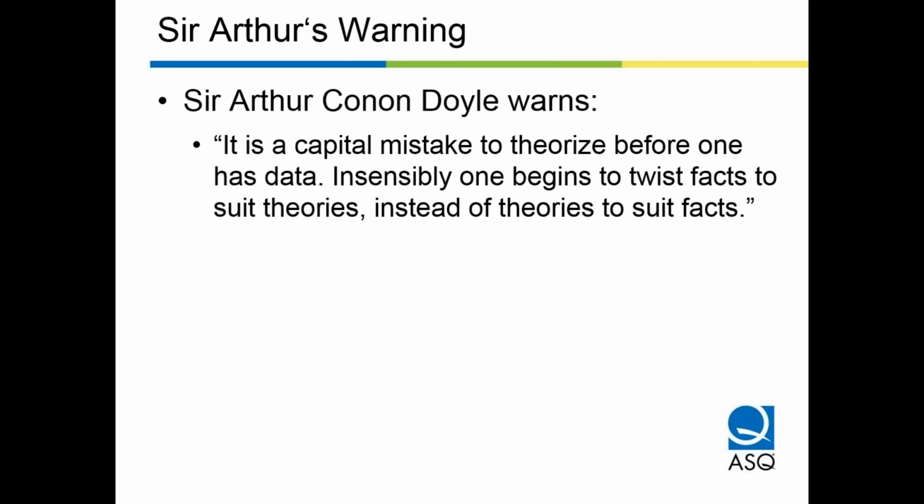Look at it, interpret that graph, form a hypothesis, by the way, using induction. Then evaluate it empirically. If the root cause is not identified, use deduction. And again, don't stop and think, was it induction or deduction? No. Look, use the information you have, form that hypothesis, get an idea, a guess at what is causing the failure. What explains the evidence in front of me? Then, how do I test that? Test it and interpret the results.